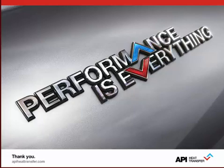All right, thank you. Another question here. What are some major problems encountered with use of shell and tube heat exchangers? The typical problems you'll see in the field are fouling and corrosion. So it's very important to discuss the fluids and the application with the design engineer, so that proper fouling factors and proper materials can be used to increase the lifespan of the equipment. By far, when we see replacement or bundle replacement requirements, it's usually because some portion of the heat exchanger has corroded over time or it's been fouled beyond cleanability.